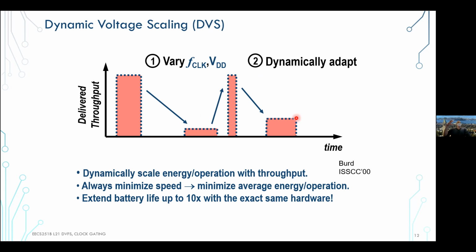Of course, there is a certain overhead in whatever needs to create these changing voltages. If you can have a perfect DC-DC converter with very high efficiency, that will be the best, with continuous tuning. But some of you who are working on that know it's not that easy. If you have an LDO, you have these overheads because it comes from a fixed supply, but it's relatively easy to put on the chip.